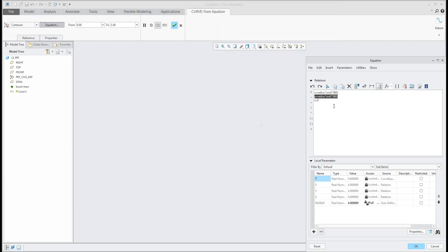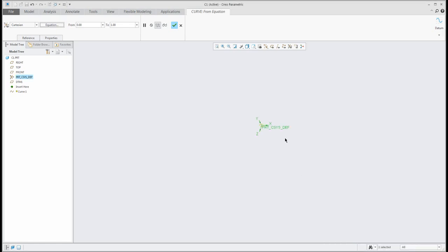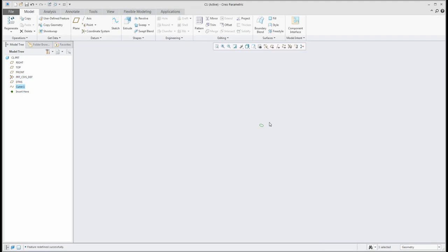Okay. You need to specify and okay. So right now you can see that I have specified every piece of information here. Yeah, change it to cosine and sine, finish, confirm OK, and finish OK, and you can see the system will create the correct curve for you. And again, if you would like to change it, you can change the parameter, no problem.